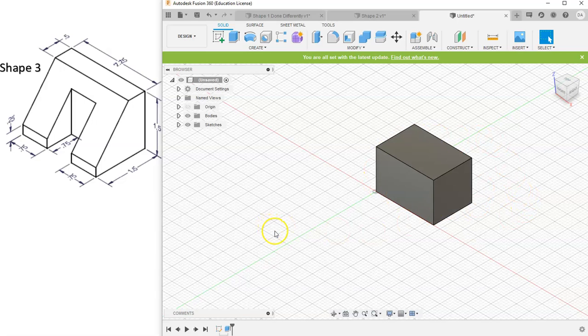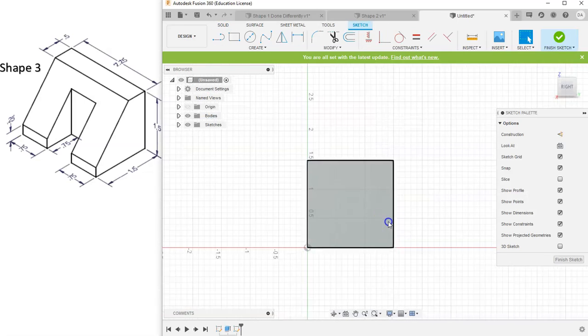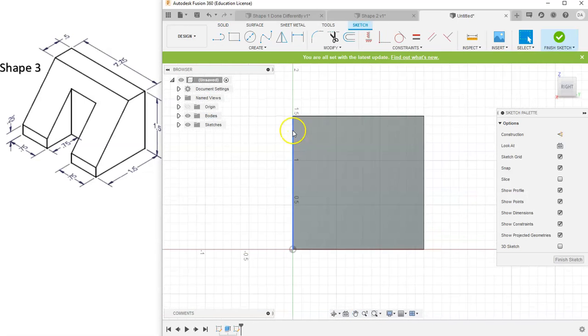And so now we have a big block which we are going to subtract from, hence the name, the subtractive method. And so the first thing I want to cut out is this sort of slant out of the side of this face. And so I want to start a sketch on the side of this rectangle. And I'll zoom in so I know what I'm looking at. And I'm going to grab my line tool to draw this slant. And I'm going to be very careful not to connect it to the center of my side or the center of my top. You can see that it's stuck to the top right now, but you can see where the center point is. It makes that little triangle. I don't want it to be in the center.